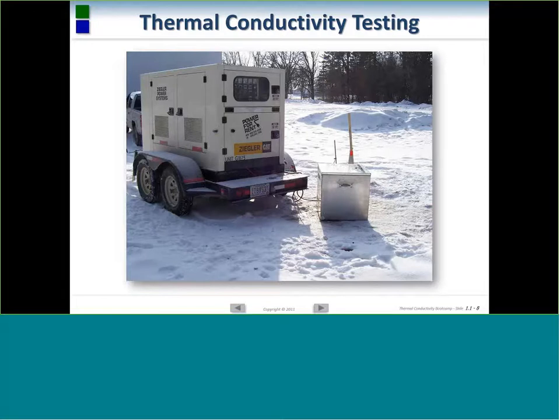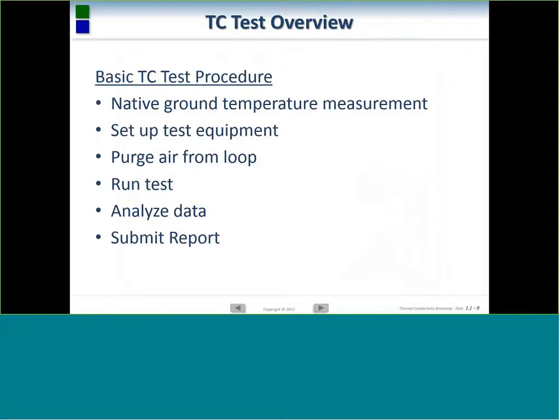Gas-powered generators have a tendency to really vary depending on the outside air conditions. I mean, at nighttime, they run very well when they stay nice and cool. Then during the daytime, when it gets hot, they have a lot more power fluctuation. Diesel generators keep the power variation less than 1.5% and stay very consistent, considering the runtime. When people run generators, they're not necessarily counting on running them for 40-plus hours straight. So we found the best power consistency comes from diesel power generation. That right there is a 30 kW unit and gives us consistent power every time. That's really the reason we run something that big and recommend running something that big, just the consistency.